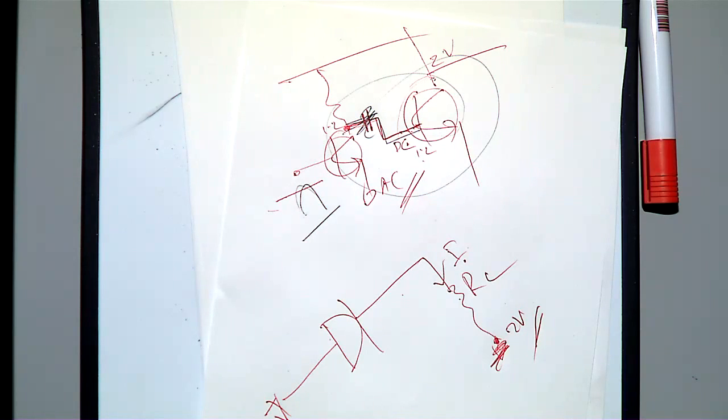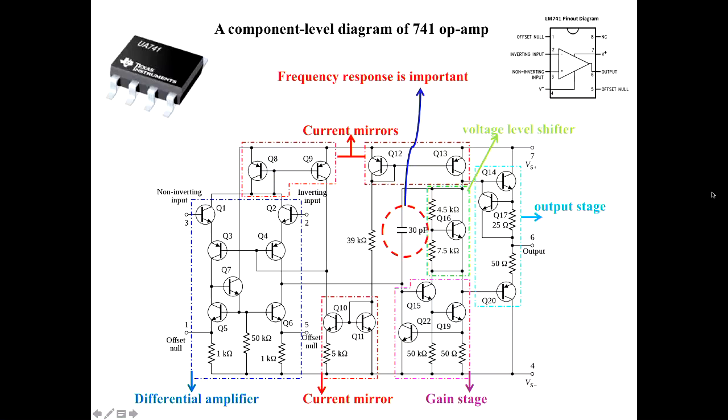But still, you can see some capacitor here. They are connected, but this is not for blocking DC or anything. When you connect a capacitor in the LM741, it will affect the frequency response, meaning the bandwidth of the operational amplifier. If you have a requirement of connecting a capacitor even to your DC coupled amplifier, like you are designing a couple of stages, and due to some filtering you use a capacitor for filtering, immediately when you connect a capacitor to your amplifier circuit, it will affect the frequency response, meaning it will affect the bandwidth.